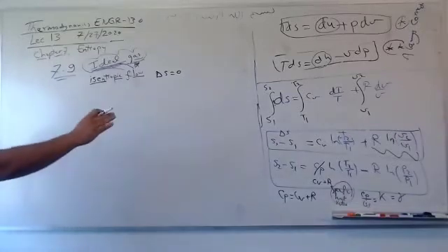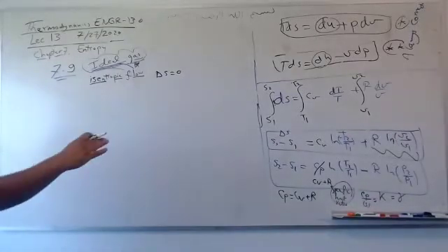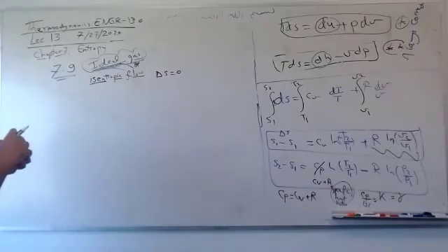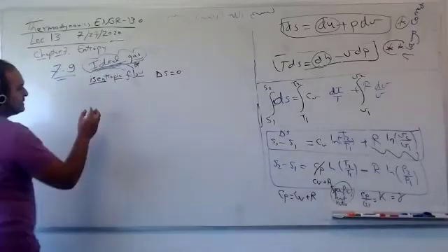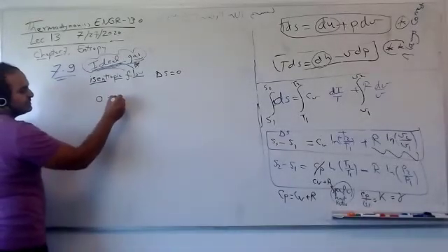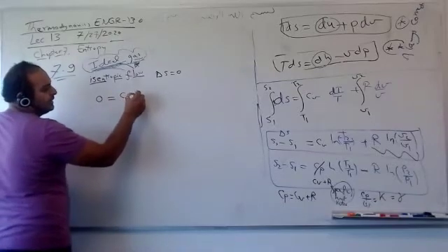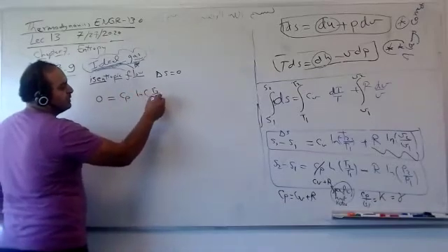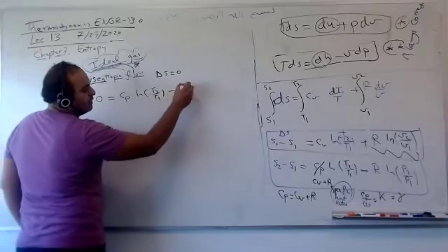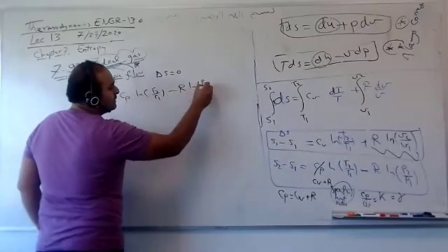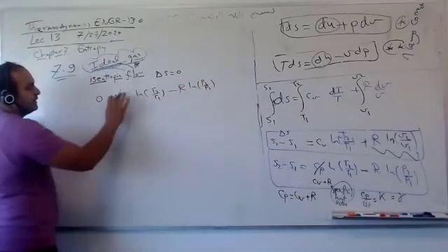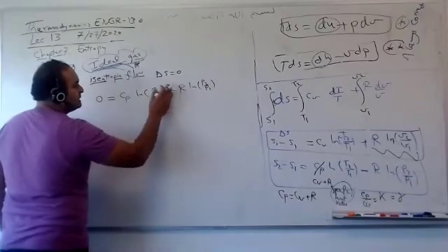So if you pick up the first equation and the second equation, combine them together, and put delta S equal to 0, for example from equation 2: 0 equals Cp ln T2 over T1 minus R ln P2 over P1. You can take the power and move to the other side.